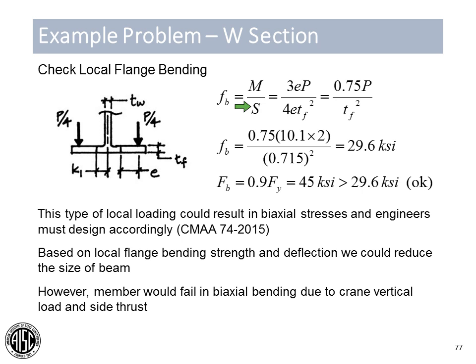bottom flange itself. So within Chapter H of the specification, there is a way to look at the stresses the way we used to with ASD design, and you should apply these flexural stresses concurrently with the overall flexural stress of the wide flange and look at the flange itself.